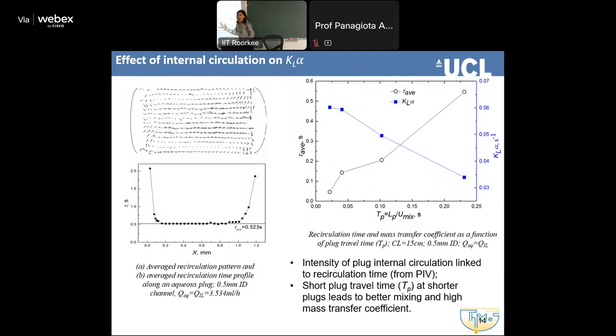And again, going back to the same idea, because I had a discussion with someone, we got some circulation times in these systems, but not by doing PIV. We're discussing how expensive it is. We did that with backlight. There is always a limit on that. If you want to use backlight, your channel cannot be very big, because then you have lots of shadows and reflections. So there is a kind of limit.